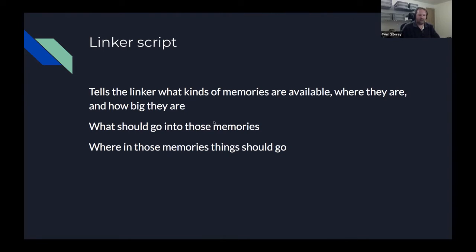And the way that it does that is using the linker script. It will then know what memories are available on the system, where they are, how big they are, and what should go into those memories, whether it's program code, read-only data like strings, or data like variables and stuff like that.